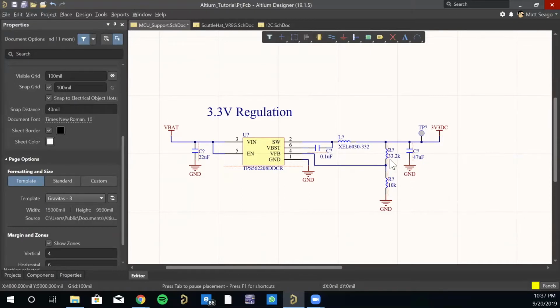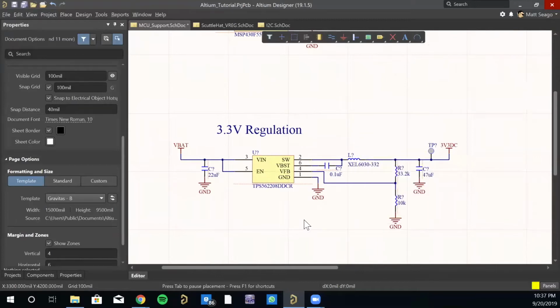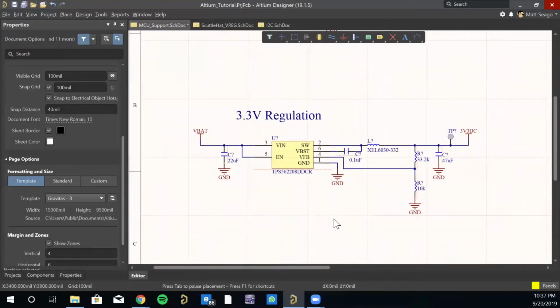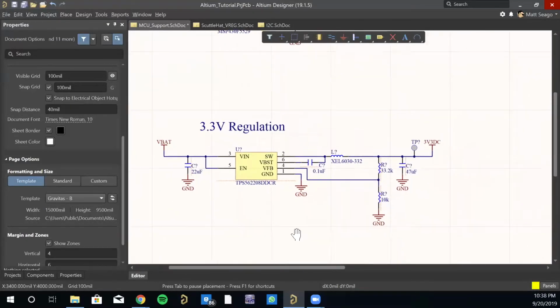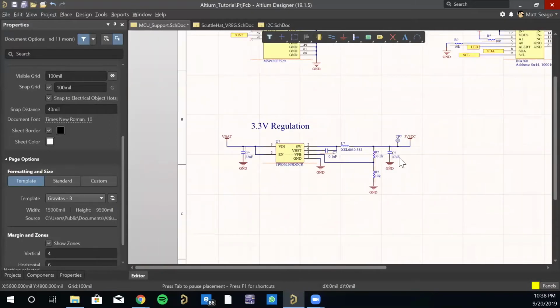But just keep in mind that resistor is very, very important. It determines the whole output of the circuit. But pretty much generally, and check the device's data sheet, everything else can stay the same. Generally. Don't count on that being the case, but pretty much the rest of the circuit can stay the same. If I wanted, say, a 5-volt circuit, I just have to change that resistor.